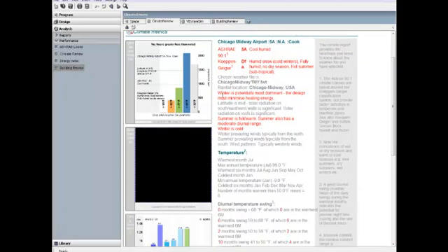Climate review provides early direction in terms of what is most important about the climate for the design development. For instance, in this example, winter is the most dominant season, which means that any building in this location will require heating. As a result, one sustainability consideration would be how to minimize heating energy, which it says here in red. Let's take a closer look at this middle chart, which is based on the Mahoney Analysis.